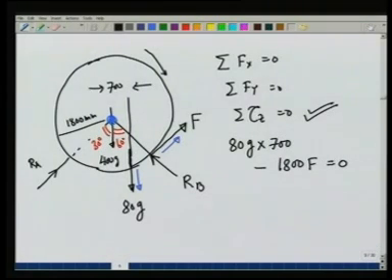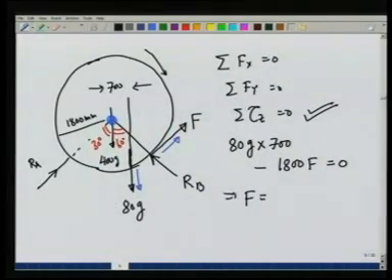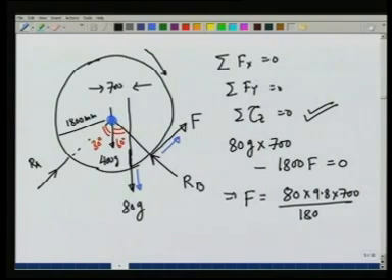Notice that I did not divide by 1000 to convert 700 and 1800 into meters, because I am using the same units mm on both, and this gives me force F is equal to 80 times 9.8 times 700 over 1800, which comes out to be 305 newtons.